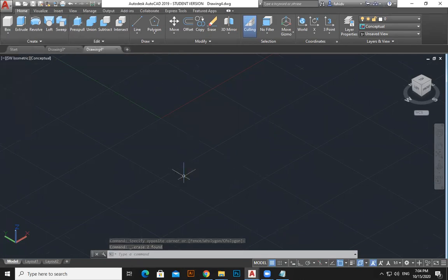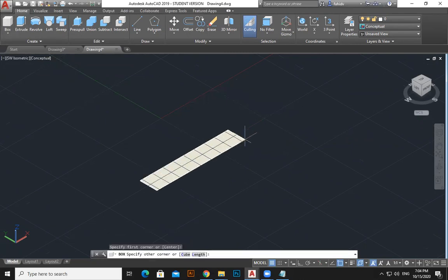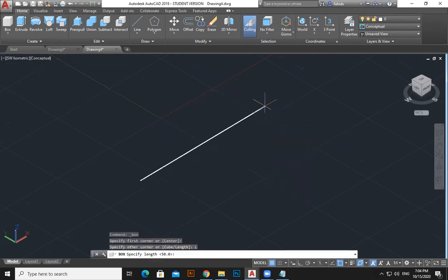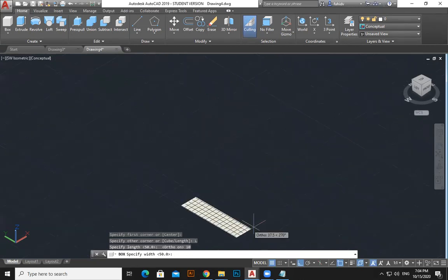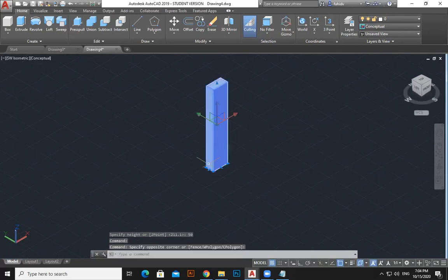And this way we can create, how to draw a box with dimensions. Take a box. Click here. Right click. Length is 10. Width is 5. Move your mouse to that side. 50. So you're going to get it like that.